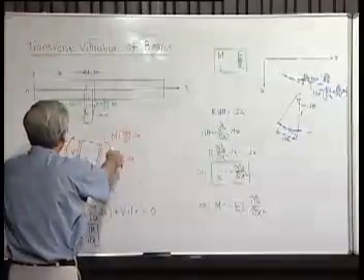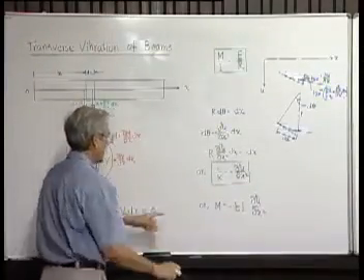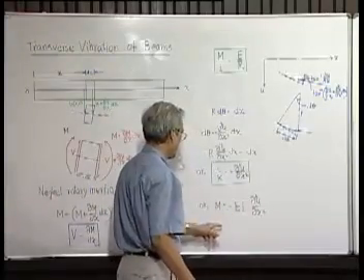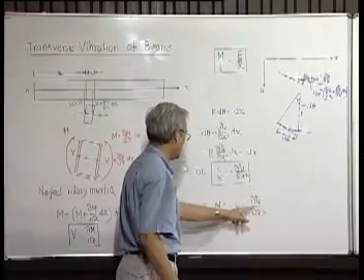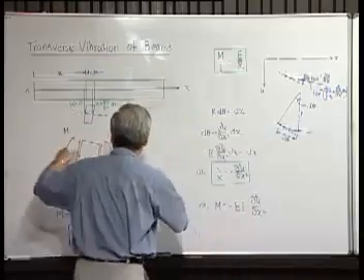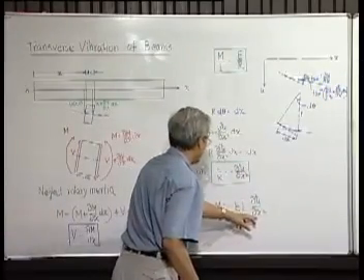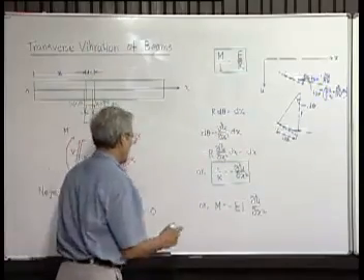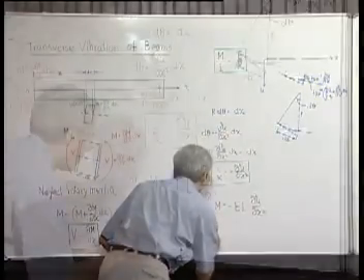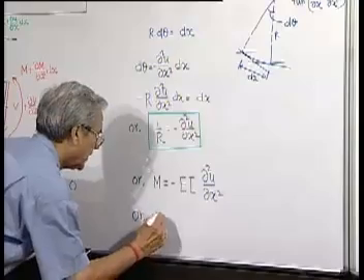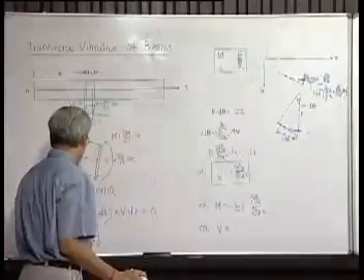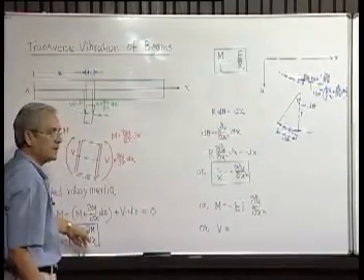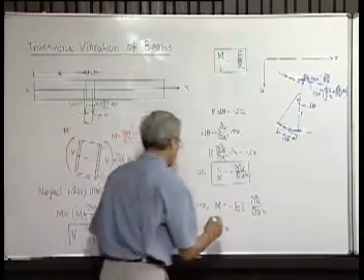This is the positive definition of m. So, to maintain this sign equality, and this is always negative, that is why for positive m, del 2u del x square is negative. Therefore, this minus. Now v, we know v is del m del x, so it will be minus EI del 3u del x cube.